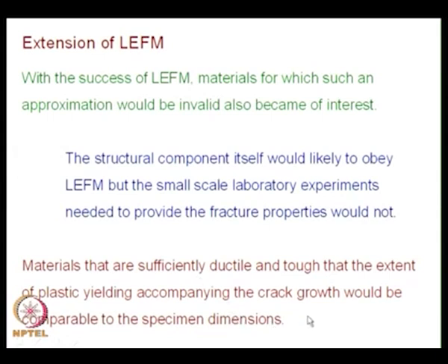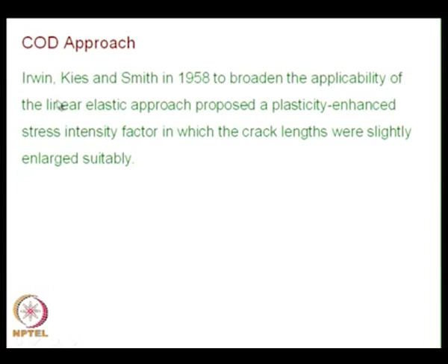And what was initially done was the work of Irwin, Keyes and Smith in 1958 to broaden the applicability of the linear elastic approach, and they proposed a plasticity enhanced stress intensity factor in which the crack lengths were slightly enlarged suitably.